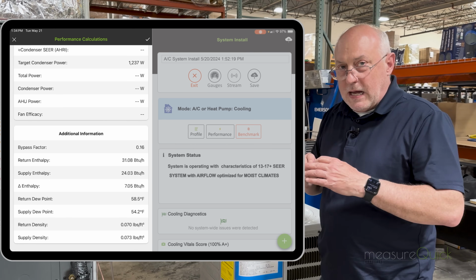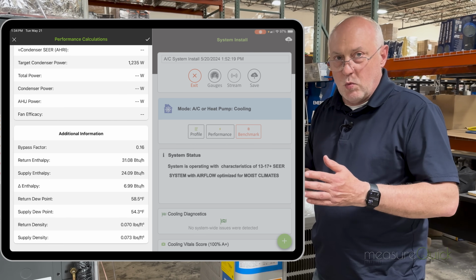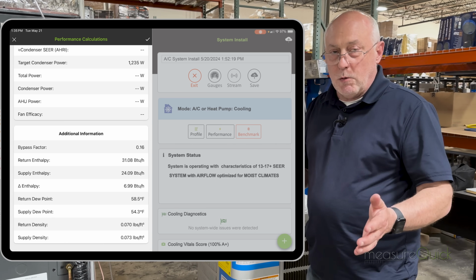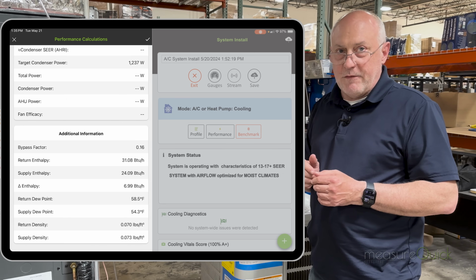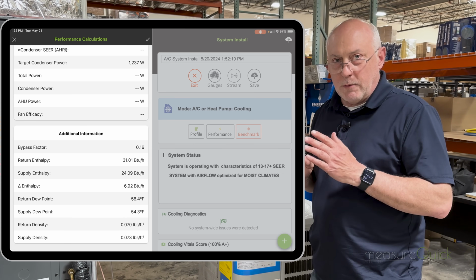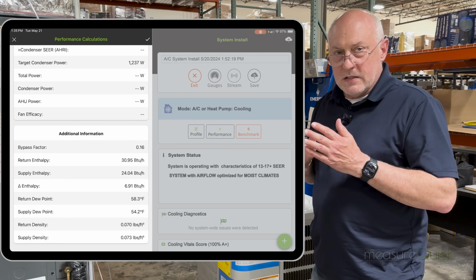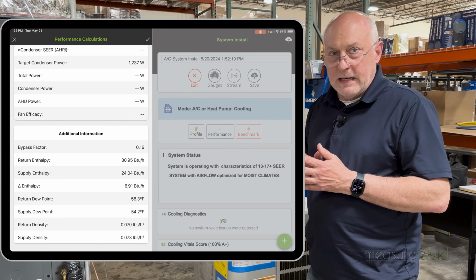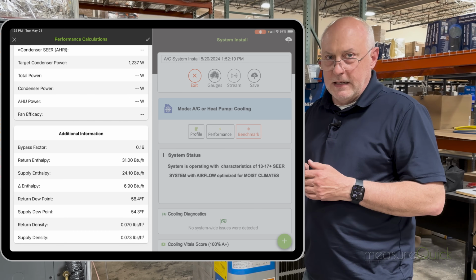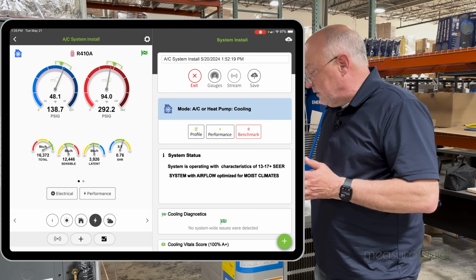So we would not want to adjust the blower on this, even though the standard CFM is low, because when the temperature and the humidity drops, the air density will go up and we'll be moving that 600 CFM that are required for this 1.5 ton system. So the airflow, when you're on a PSC, always pay close attention to the actual CFM, not the standard CFM. On an ECM motor, we almost always look at the standard CFM airflow. All right, so we got all those things right.